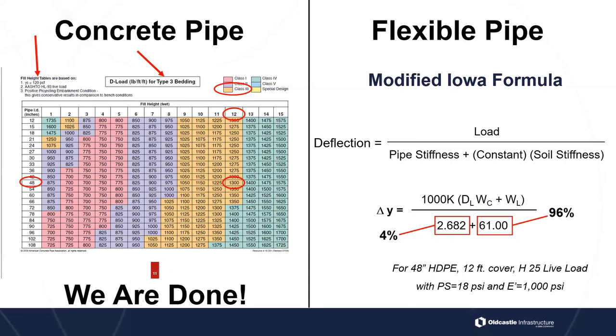And when I add those together, and I take the ratio of what each of those values on that denominator are, and keep in mind, this is the ability to withstand the load under a certain amount of deflection, right? The pipe portion of that only accounts for 4% of that number, while the soil accounts for 96% of that. 96% is related to the soil.